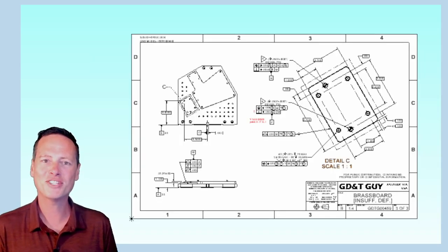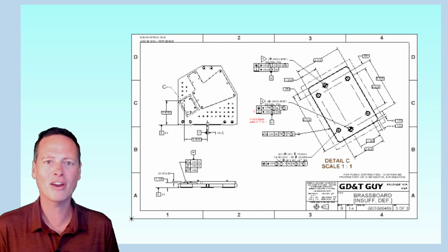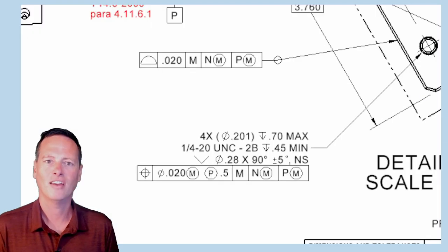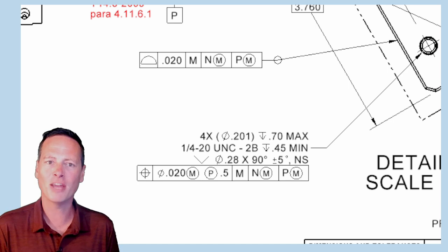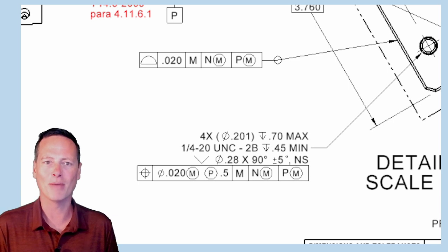By the time we get to sheet 3, the idea is that datum reference frame A primary, B secondary, C tertiary at MMB is already established. And then here in the detail view, we are talking about datum reference frame M primary, N secondary at MMB, P tertiary at MMB. So how do we get from ABC to MNP? That's in these views on the left.